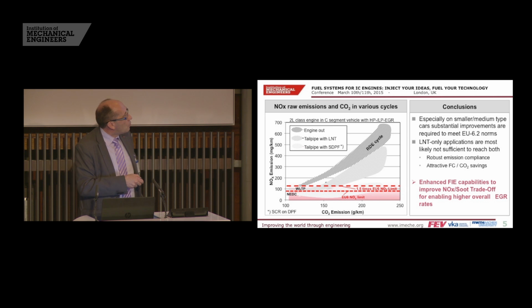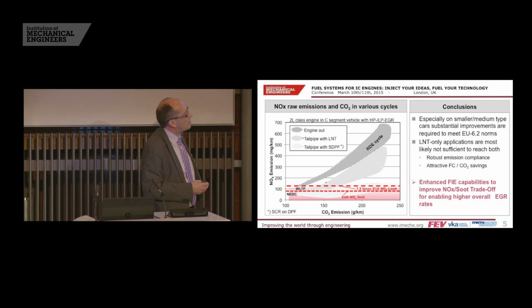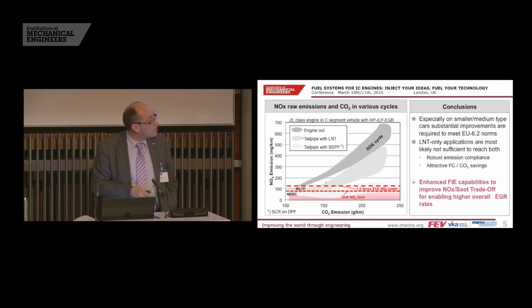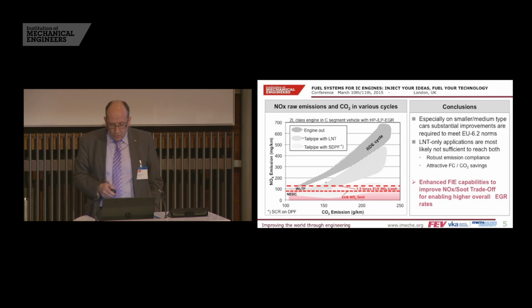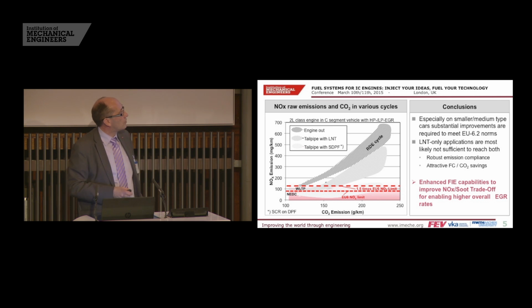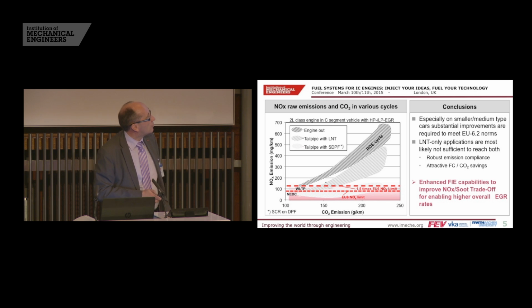So also here we have to work in order to improve a better EGR tolerance at higher engine loads, just referring to the motorway operational conditions which I showed before. And in order to have a good improved NOx-soot trade-off, we have to work on the fuel injection equipment as well. And this is what we do, of course, for our customers, but also within our internal research.